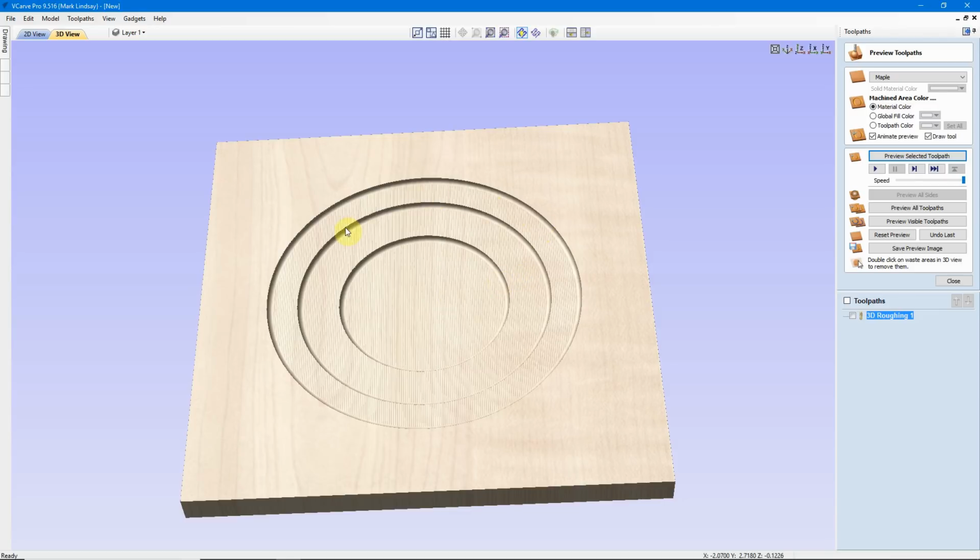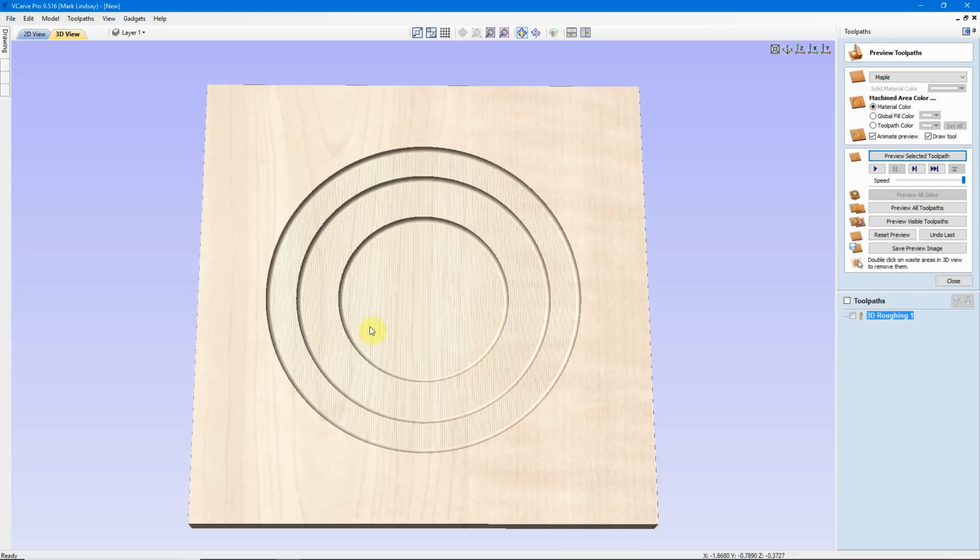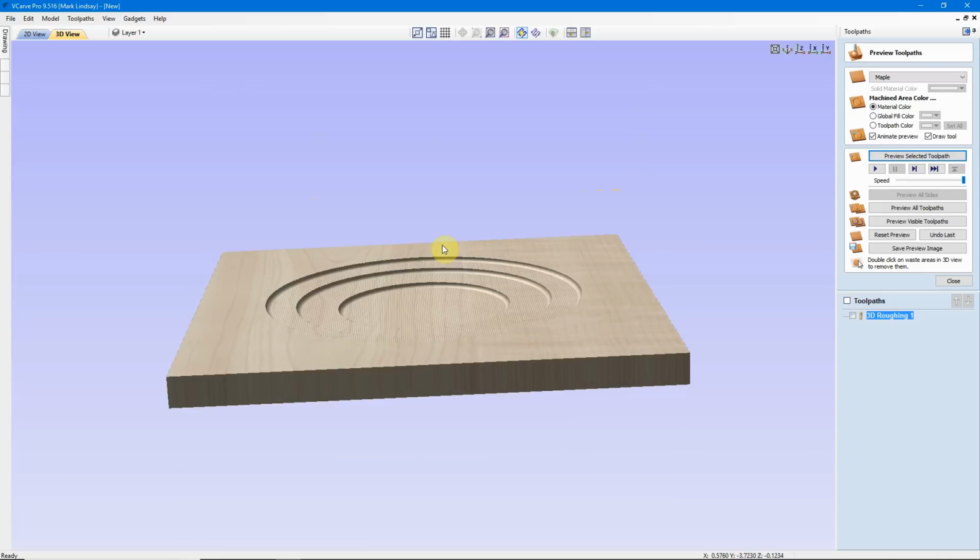So I need to remove the bulk of this material with a roughing pass, leaving only that 25 thousandths, so I know that my bit isn't trying to carve away too deep into this material. I know that the shaft of the bit, where there's no cutting edge, is not going to hit uncarved material. That's why I do a roughing toolpath. Again, if you have a tapered ball nose, you may decide you don't need to do that. I have to do that. So, there's our roughing toolpath.